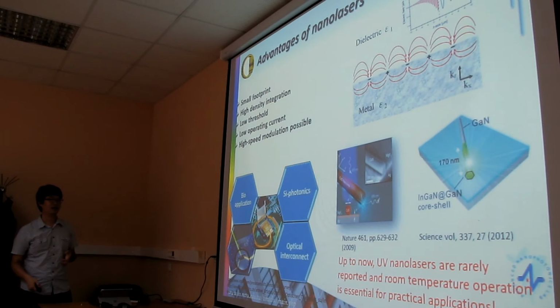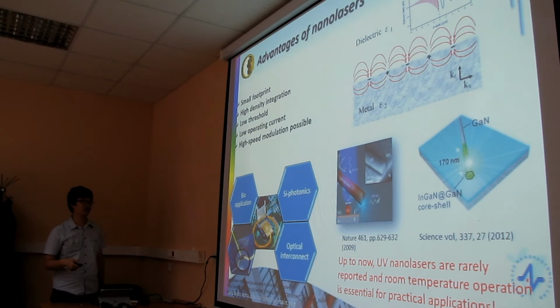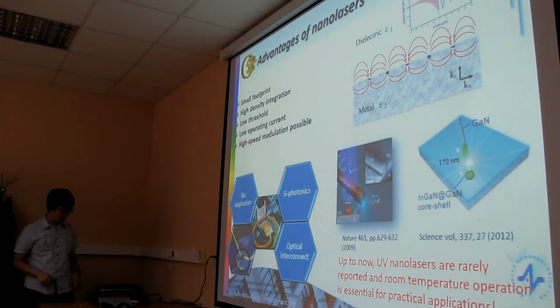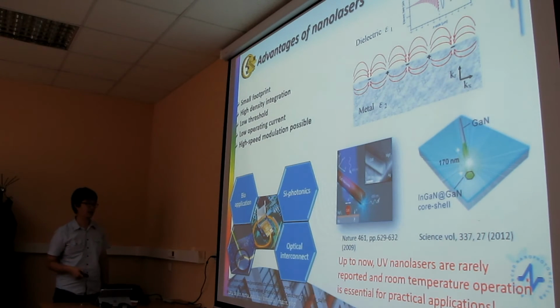especially our latest research on aluminum surface plasmon. It is a CMOS integrable process. And finally, it can be used in optical interconnection. There are very few articles talking about ultraviolet emission in the surface plasmon polariton nanolaser. This is why we chose zinc oxide as our material, because it emits in the ultraviolet region.